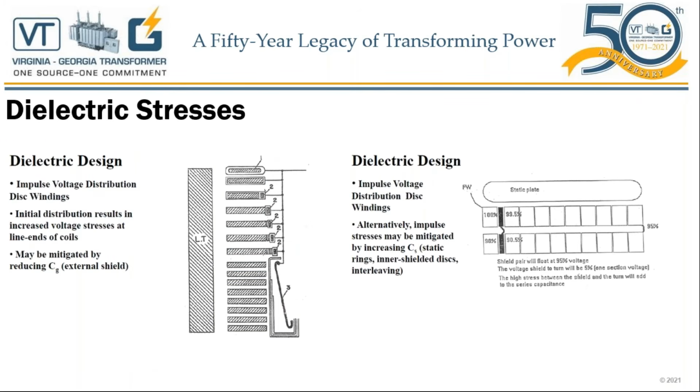Knowing that the impulse stress needs to be managed initially because it's so quick, the first 3-4 microseconds are the most important. And the capacitor has to take that first, as I always say, the first punch. We look at how we can increase the capacitance value at the start of the windings to withstand these dielectric stresses. So I put some illustrations here for you.